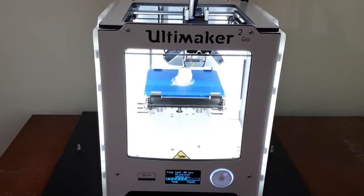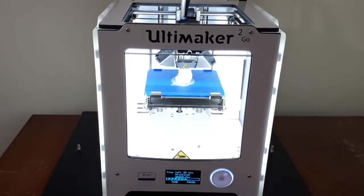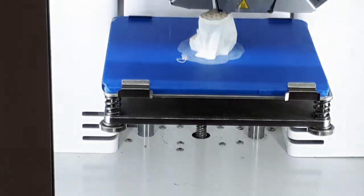The library's 3D printers use fused deposition modeling, which works by heating the material and extruding it out of a nozzle. The nozzle moves horizontally and vertically across the build plate. The build plate moves down to accommodate each layer.